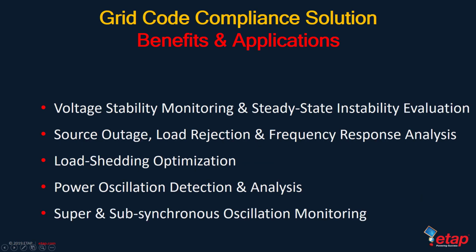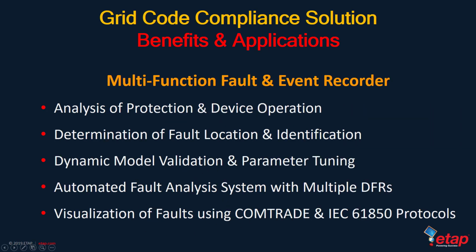You can also use it for additional capabilities such as voltage stability monitoring, power oscillation detection, as well as subsynchronous oscillation monitoring. And it also is a multi-function fault recorder, so therefore you can also use it for the analysis of protected device operation and combine it with the ETAP AFAS or automated fault analysis system to determine the fault location and identify the type of fault in the network.